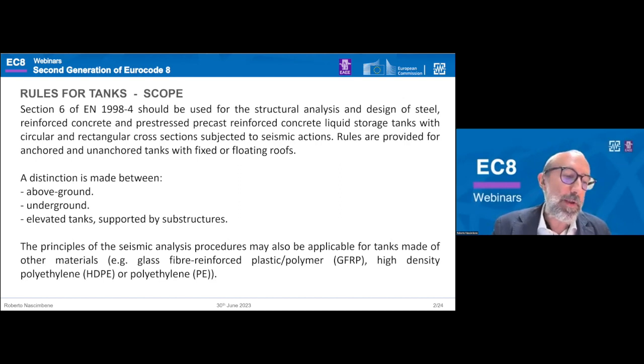When I say only the principle, I mean that the definition of the limit state, for example, of the safety verification for materials other than steel and concrete, steel and precast concrete, are not covered by the standard. Principles means, for example, equivalent mechanical model that we will see later, and so on, but not the definition of limit state and safety verification.